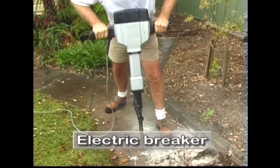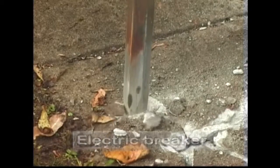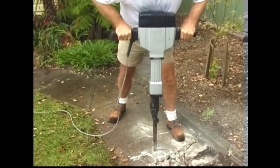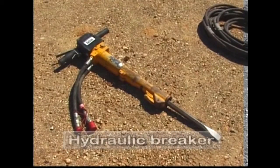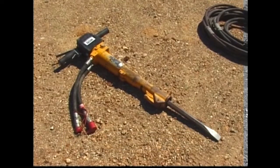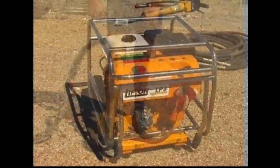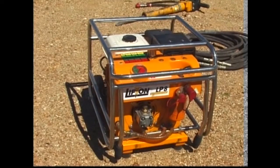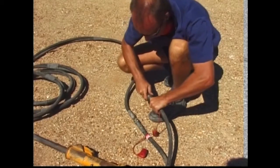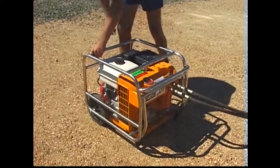Heavy-duty demolition tasks can be addressed using breakers. The electric breaker is convenient because it requires only an electric power lead for operation. The 25 kilogram hydraulic breaker is relatively light, but outperforms heavier pneumatic breakers. Power comes from a hydraulic pump circulating oil to the tool through supply and return hoses. The portability of the unit allows access to difficult sites.